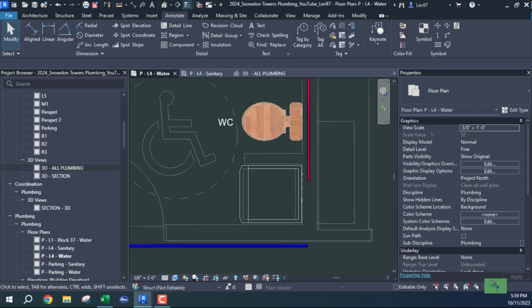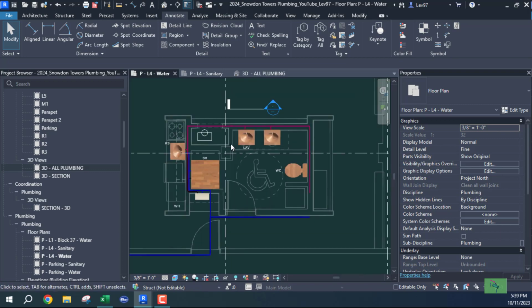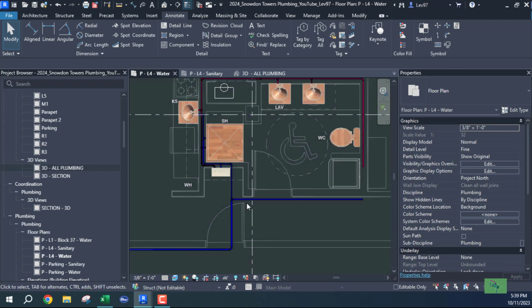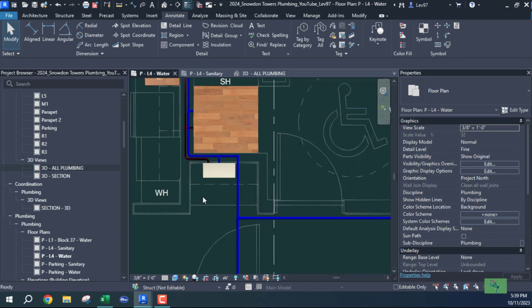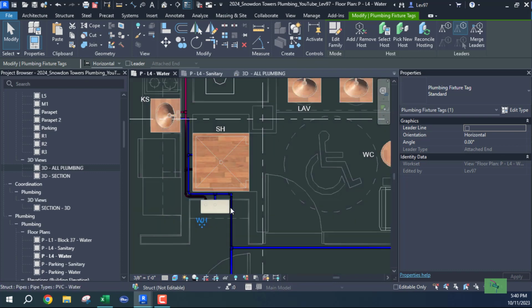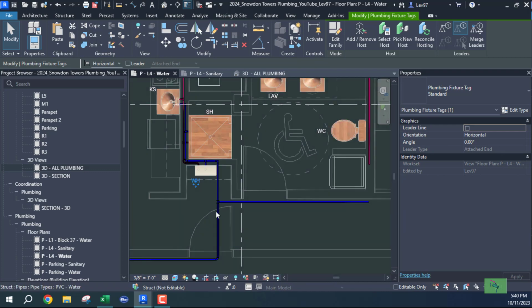Okay, so let's continue working on this plumbing project. I left off with cold water. Looking at this bathroom, the blue line is the cold water and the red is the hot water. This is the water heater, and the hot water and the cold water are going around. I'm supplying the left side of this bathroom with cold water, and on the right side I'm going to use my pipe that's in the ceiling to go over.